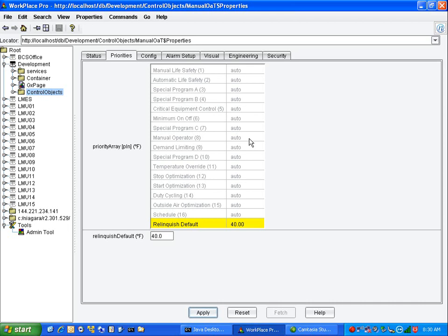Now I'm going to have a class strictly on remote local set points, I call it. When we have jobs that have S3, S-Link sensors down there and we want to give the customer capability to right click on an object and use either the local set point or the remote set point, we can do this in any generation of controller, whether it be LAN, BACnet, or Network 8000.